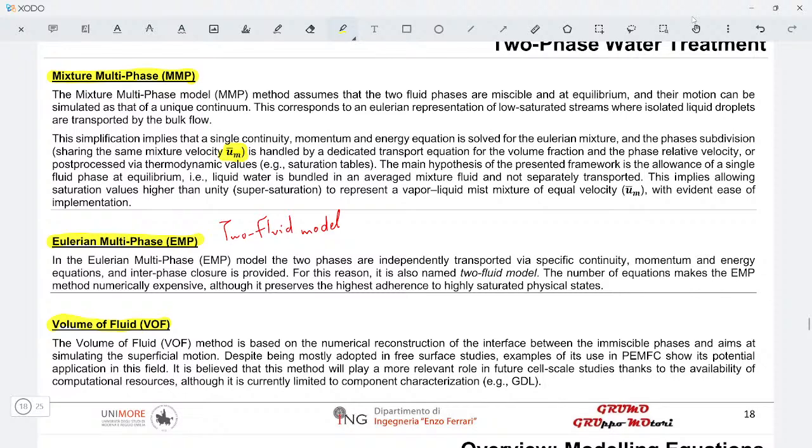Okay. So these volume of fluid models are very popular in sloshing or mixing problems, or in oil jets or water jets. Especially in recent years, they make large use of mesh refinement techniques, something like adaptive mesh refinement, because clearly, if you want to reconstruct the surface,